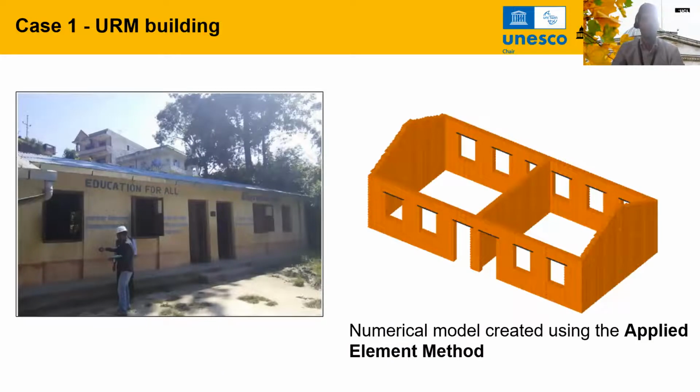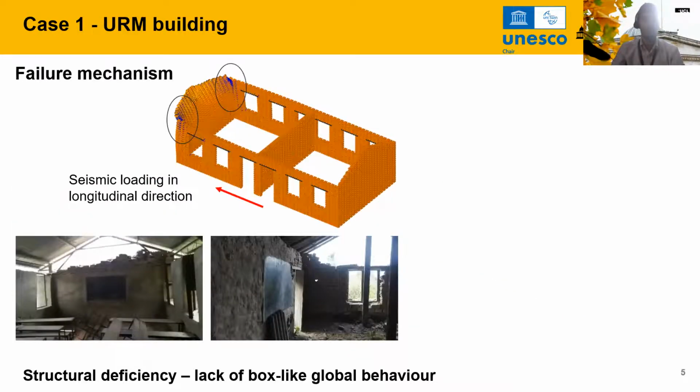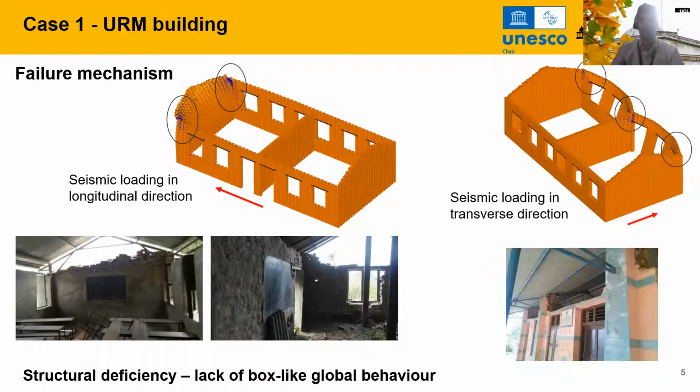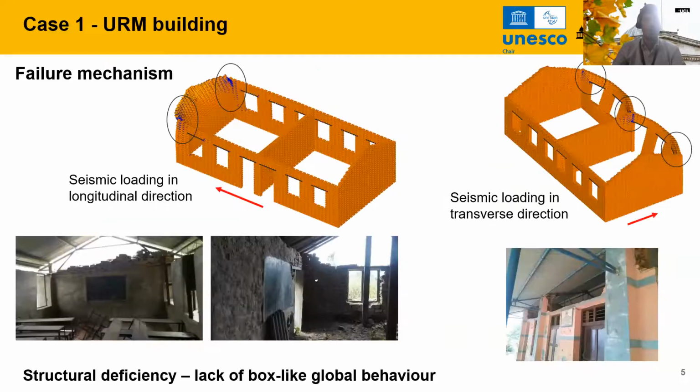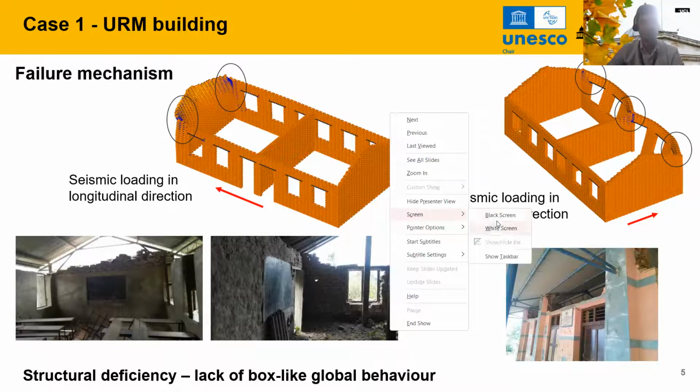So, numerical model using applied element method. This is how it behaves during the earthquake in the long direction. This is how it behaves during the seismic loading in the short direction. Okay. Now, because this building lacks global box-like behavior, we want to analyze this